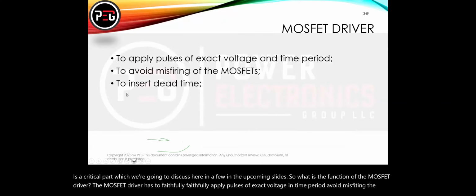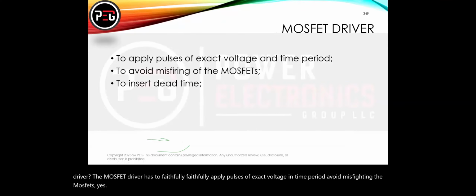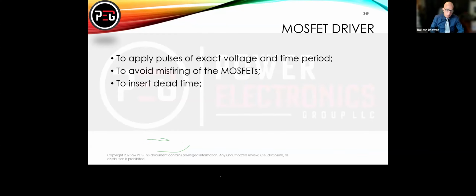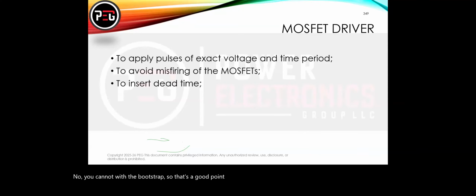Sir, with the bootstrap strategy, we cannot, however, go to 100% duty cycle. Correct. Yes, you cannot go to 100% duty cycle. Is there any instance where you have seen that we go for 100% duty cycle in motor control? No, you cannot with the bootstrap. That's a good point. But in terms of motor control, is there any instance where we are forced to go to 100% duty? Maybe we'll then not use bootstrap.